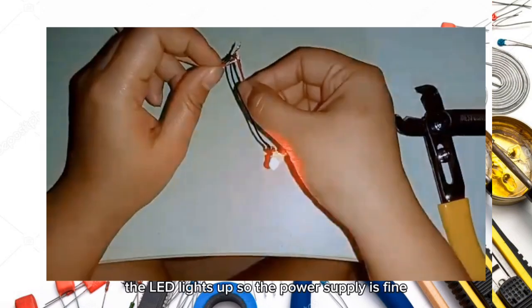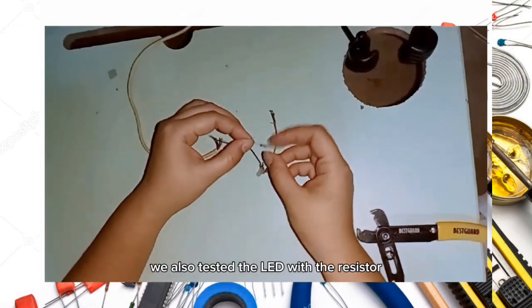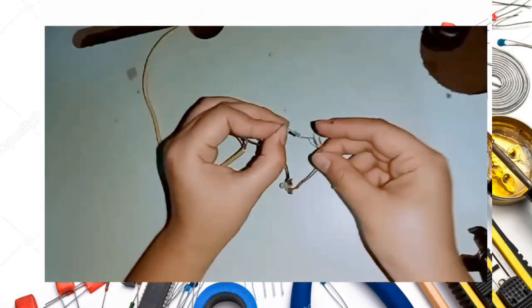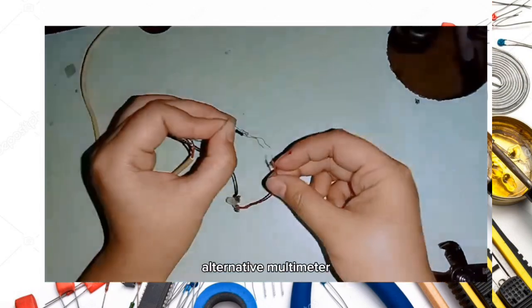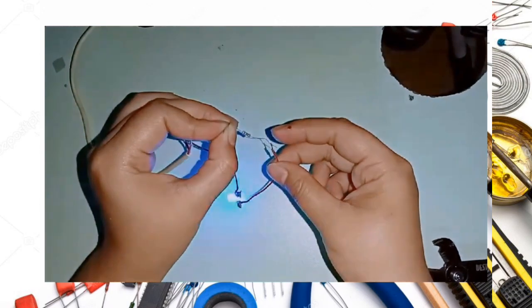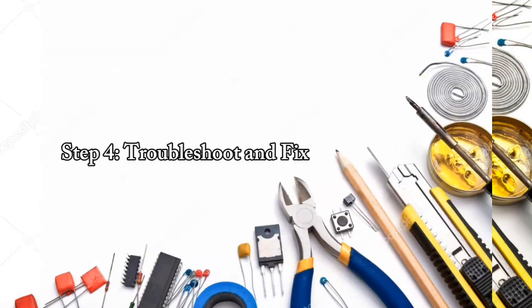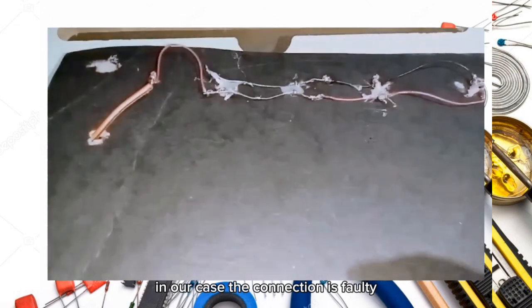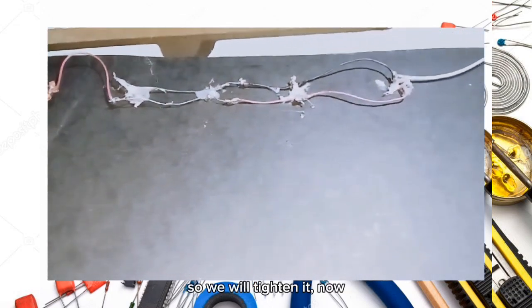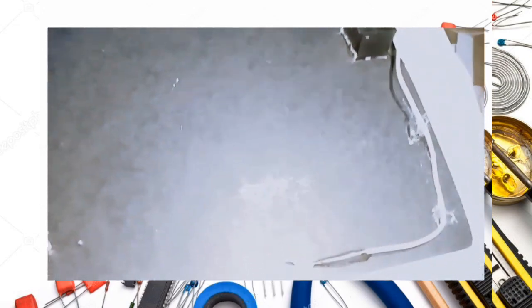The LED lights up, so the power supply is fine. We also tested the LED with the resistor. All the LEDs were tested using our improvised alternative multimeter. In our case, the connection is faulty, so we will tighten it. Now, let's reconnect everything and test the circuit again.